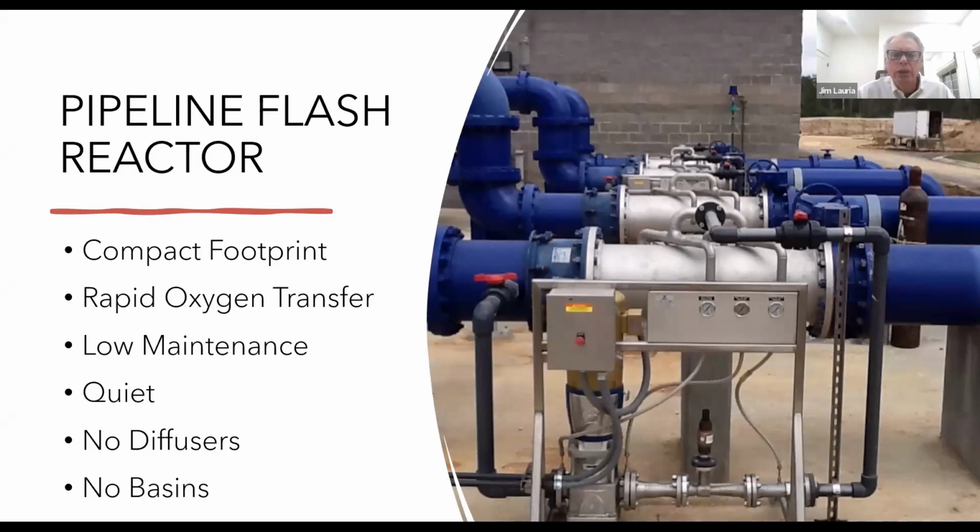systems there. So it's a compact footprint. You get very rapid oxygen transfer in just a couple of pipelines in the system. Low maintenance. It's quiet. A lot of times if you're using blowers or these diffusers, you get a lot of noise. You've got to protect the diffuser, the blowers in some kind of housing. And as I said, no diffusers and no basins. So you're talking about a lot less civil works. If you're doing it in a pipeline, you don't have these basins that can take a lot of steel and concrete.